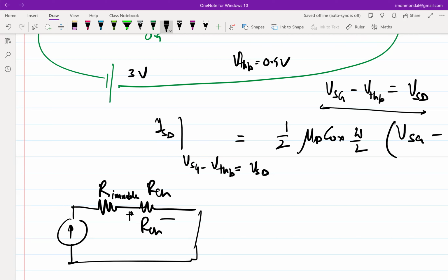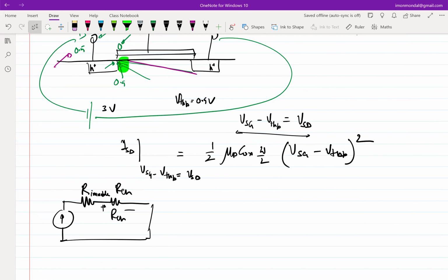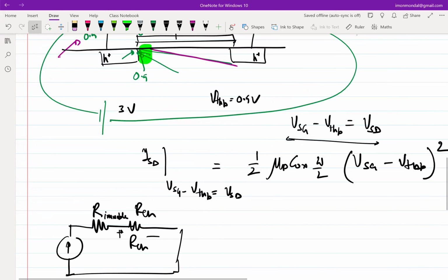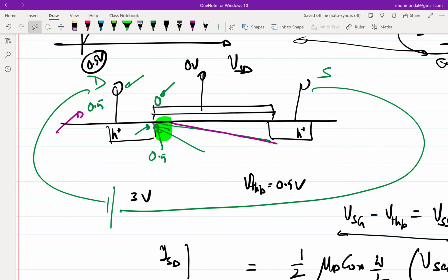Right? So the extra drop, in this case, I have shown with respect to a current source, but if we apply a voltage source, that extra drop will accrue on that immobile part of the channel. And because that extra voltage drop will accrue on the immobile part of the channel, the amount of channel that will shift will be very small, because with even a small amount of shift, you will be able to accommodate for that extra drop. So for all practical purposes, you will not see any shift of this triangular profile.